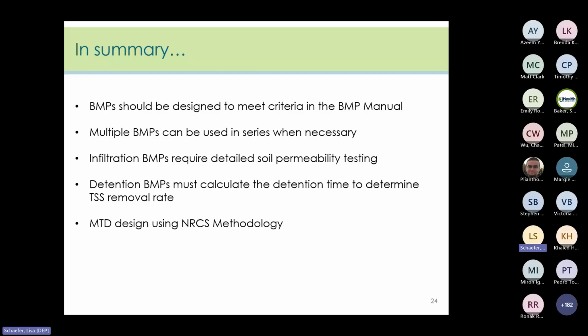There's also something that you need to consider if you're swapping out an MTD for a different one. All right. And reach out to us if you're unsure about the sizing. There's been instances where a filter type MTD was replaced with a hydrodynamic MTD. And unfortunately, too small of a model was selected. And that resulted in serious water quality issues and flooding.